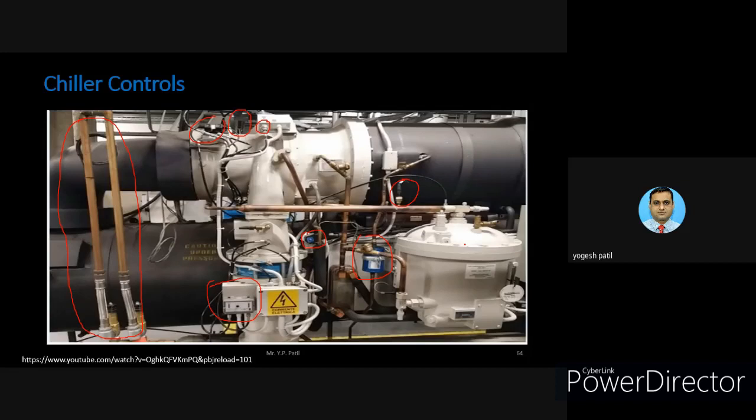There are the condenser section as well as the chiller water section. From the evaporator there is a chiller water section, and in the condenser there is a condenser water section. So there are two water loops in a particular chiller. One is at the evaporator, another is at the condenser. How those loops are behaving, the chiller must know that.